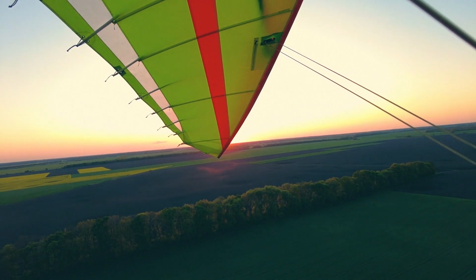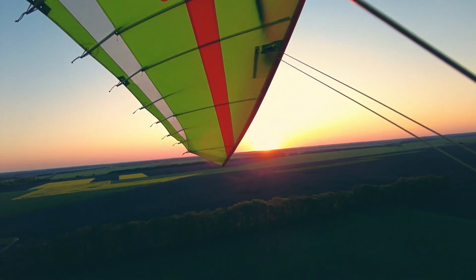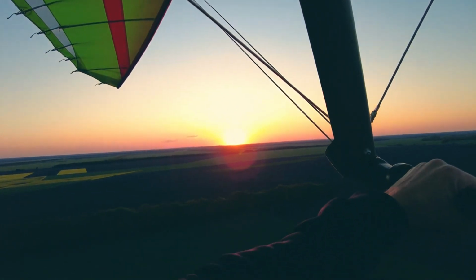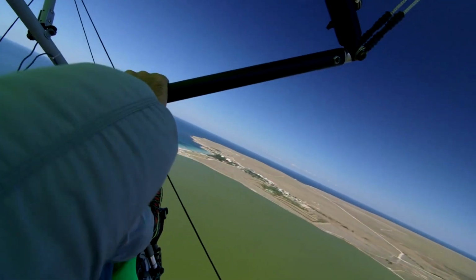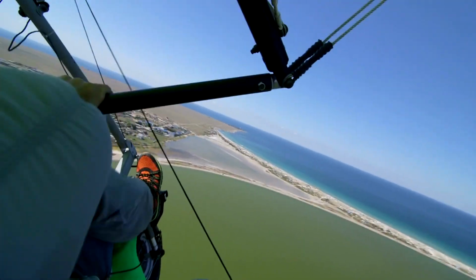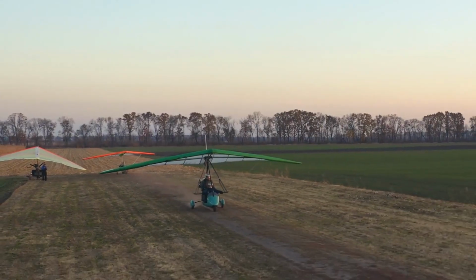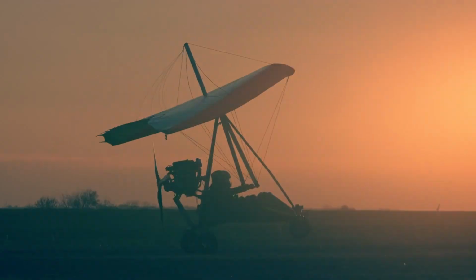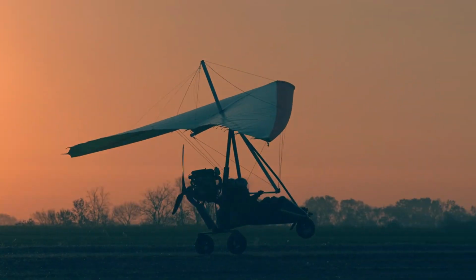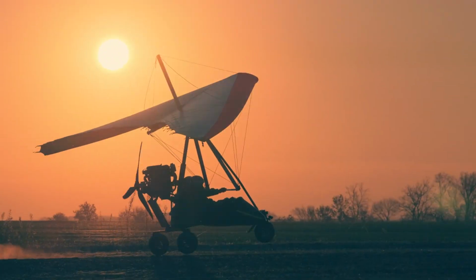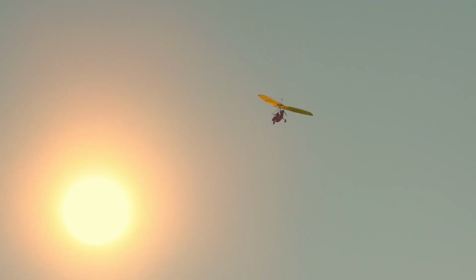The WSC wing maintains its airfoil shape through rigid preformed ribs called battens, supplemented by additional ribs in some double-surface wing designs. These ribs, despite their rigidity, allow the wing to be termed a flex wing for two main reasons. Firstly, the outboard leading edges of the wing are designed to flex up and back when loaded. This flexing provides load relief, reducing wing loading and increasing twist with greater weight, resulting in a smoother ride in unstable air. It also assists in initiating turns.